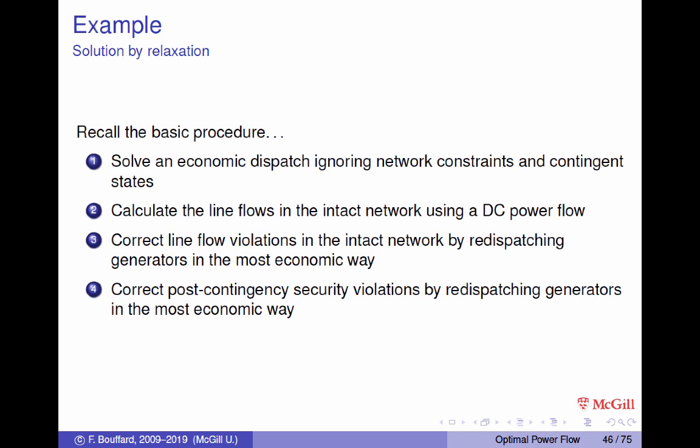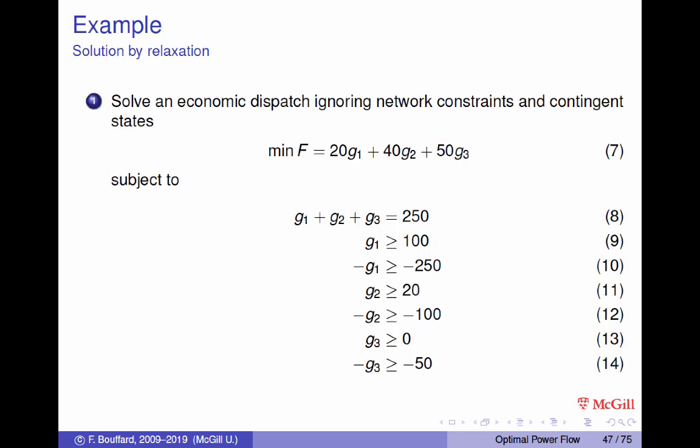And in the fourth step, we're going to be doing the exact same thing, but we are going to be degrading or taking out some of the transmission lines here, and we're going to redispatch to make sure that our precontingency dispatch will be able to survive the loss of any one branch in this network. And at the same time, we're going to see what's the impact on the cost of operating this power system as we are slowly but surely adding some of these constraints.